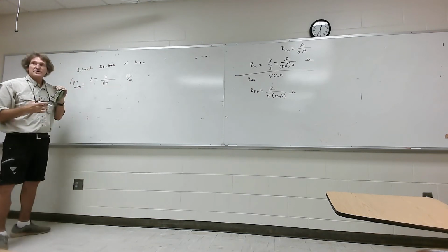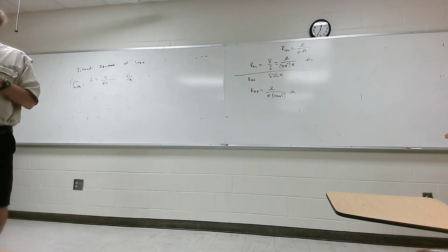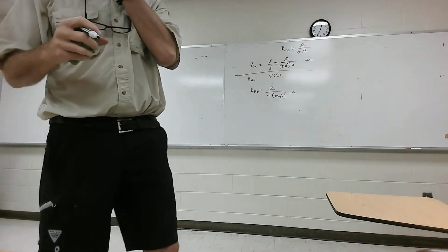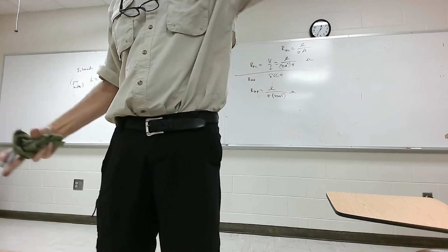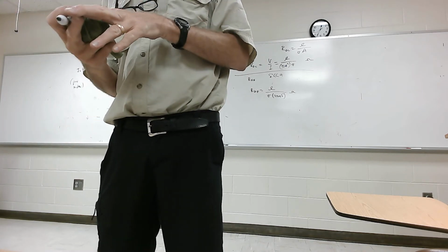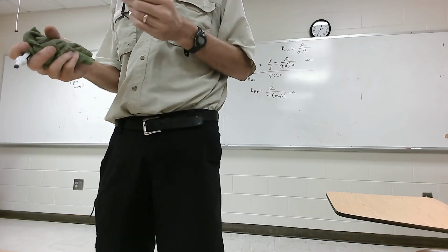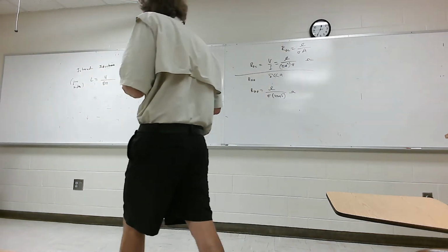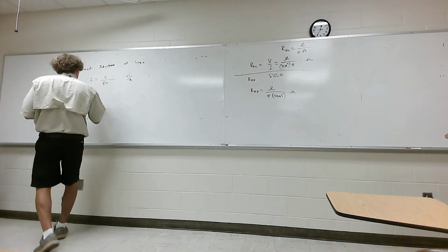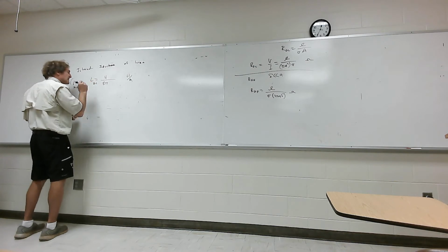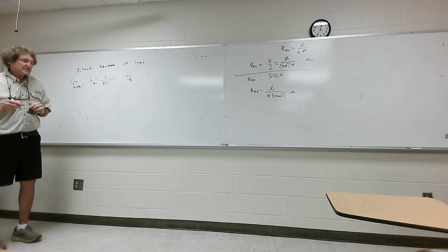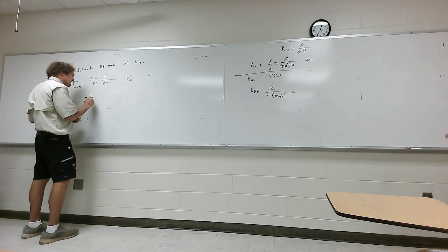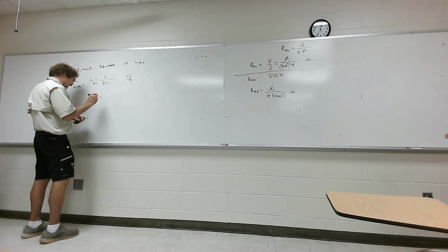What's the one thing that should astonish you, or at least seems to? It's not a function of radius. It doesn't matter if the radius is 1 meter or 1 micron. That's the internal inductance, and that's a unique feature of this. But this is the DC. So make sure you put that down. DC internal inductance.